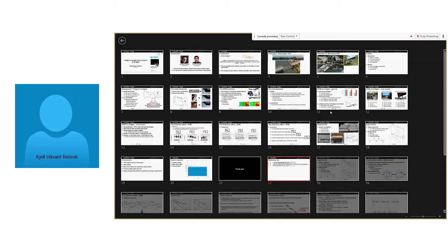We are also discussing steel qualities, as you have studied here. For the time being, we have landed on our 420 quality. But we can see that fatigue is a dimensioning factor for us. Yes, it's very interesting, and the weight saving that you indicate also applies to the buoyancy need that we have. So if we can save a ton in the main girder, we can also save a ton in the need for buoyancy. Exactly. So we have a double effect on floating bridges.